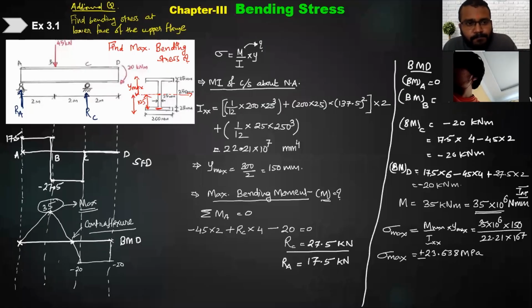Sir, we are talking about the bending stress at the lower face of the upper flange. That means y will be 25 mm below, so y max will not be there.